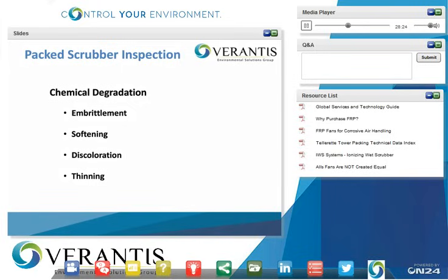Embrittlement can occur in the presence of strong oxidizing agents. Chlorine is an example. Concentrated nitric acid is another. That doesn't mean you can't use polypropylene packing for chlorine scrubbing. Many systems have that, but if you have extremely high concentrations of chlorine gas coming in for, say, an emergency scrubber, then in some cases people will consider a different material that won't have the embrittlement problem. Basically what's happening is an oxidation of a plastic, and when you oxidize a plastic, it gets harder and it can crack. You've seen sun oxidation damage plastic that's left outside. That's basically what's happening inside a scrubber if you have the right chemical conditions.